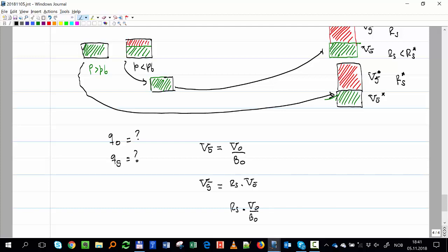So we see that this didn't happen for oil. For the surface flow rate, or the surface volume of oil, I just had the contribution from oil. Oil became smaller and smaller and eventually became surface oil. Nothing else to see. But for the gas, part of the contribution came from the local oil that was vaporizing and vaporizing, but not all.